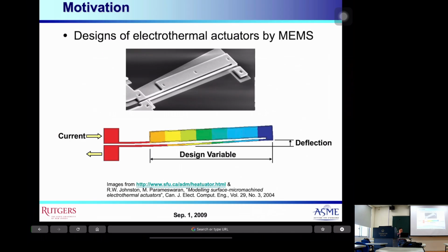It's a story that we want to work on MEMS, and from the literature, it says this kind of device can be like a micro gripper when you apply current to the silicon structure. Because the two sides of the finger have different dimensions and so different thermal expansion, when you apply current, it's being heated, and it's gonna bend toward one direction.